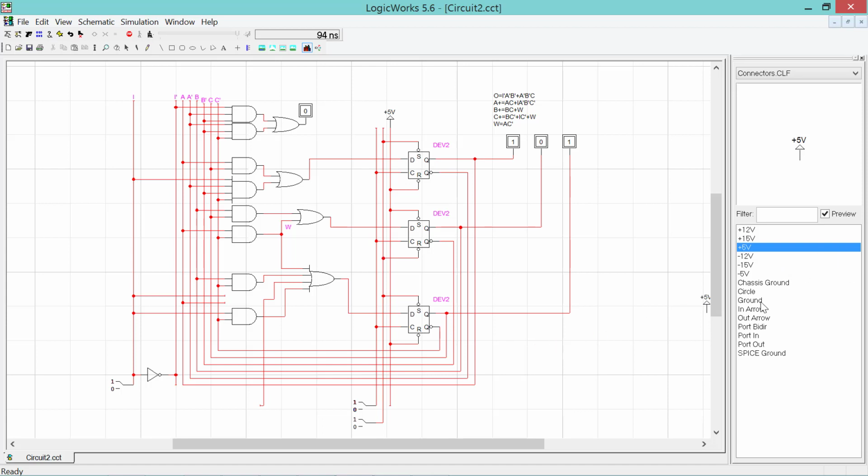This is an OR gate. If we connect with a logic 0, then we are ORing with 0, which means ORing with 0 is a null operation. We can simplify. I will remove some extraneous wire here. And let's try clocking now to see if we can go from state 101 to 100. 101, check the output at 0. Clock, it goes from 101 to 100. Okay.